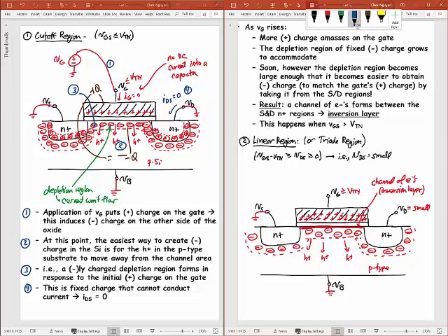And so all that I said is actually written above here. So we're at more positive charge here. You can label that 1. So I'll label that 1 right there, leads to a depletion region of negative charge that grows. So this has grown, say, from its original thickness, which was there, to there. So I grow that depletion region there.